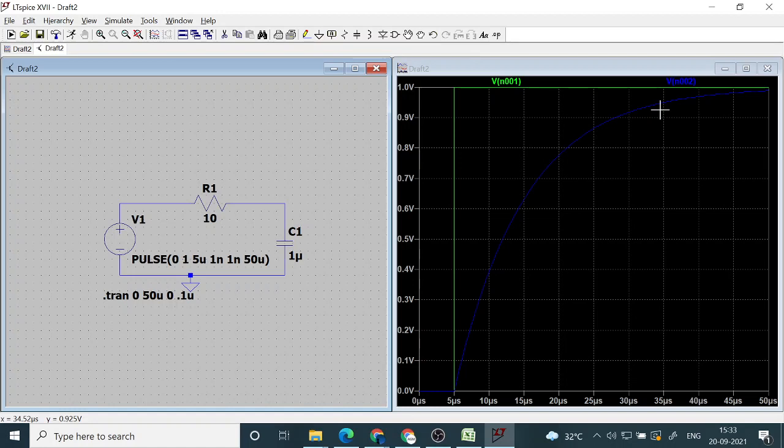Now in signals and systems language you can say this is a linear system, to which you give this x of t as input, and this is your y of t output. How to calculate y of t for the given x of t? The input is basically a step function, but it is delayed by 5 microseconds, so u of t minus 5 micro, that is this.